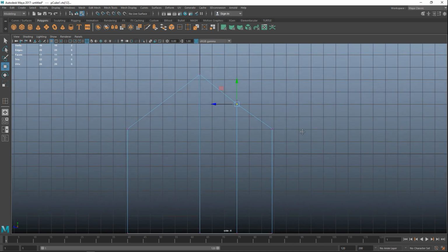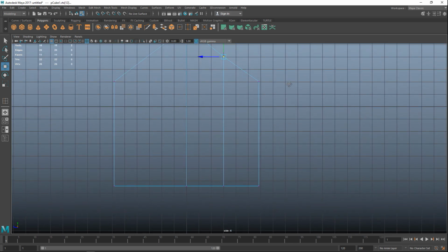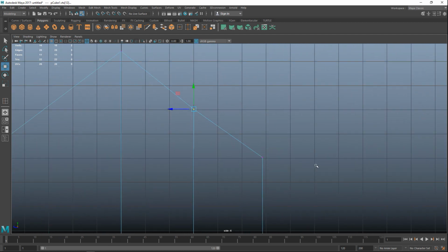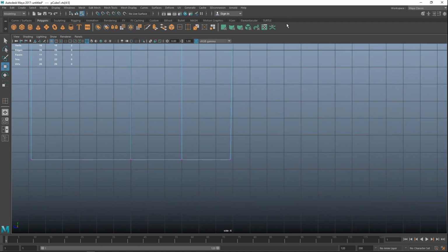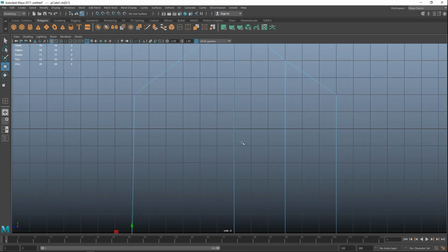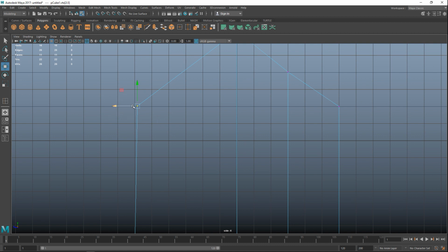Okay. So the other thing we can do here is we can snap to grid, which will kind of help us later on. So let's do that. We'll just take that and hold down X and move it. And we'll do the same here. We'll just hold down X, and then we'll snap all these vertices to our grid so it's nice and clean, and from a measurement point of view we don't have to worry about that too much.